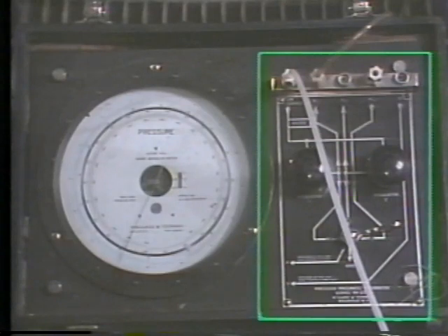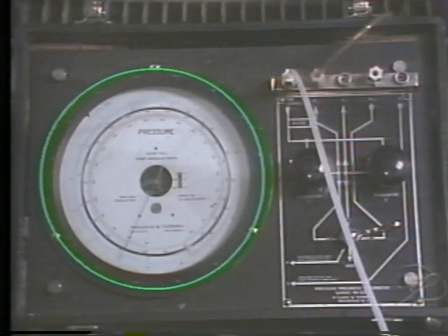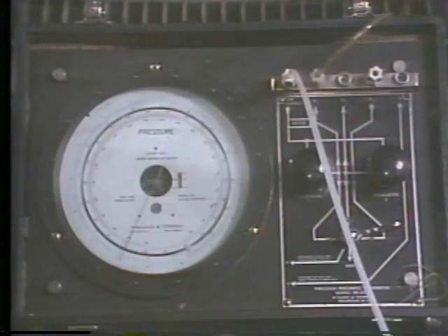This instrument has a regulator that allows the technician to control the air pressure going to the positioner. It also has an accurate pressure gauge that indicates how much air pressure is being supplied to the positioner at any given time. The instrument you use in your work may look different than this one, but it serves the same purpose. This instrument temporarily replaces a controller and is used to manipulate the flow of control air to the positioner so that the technician can make adjustments at different control air pressures.